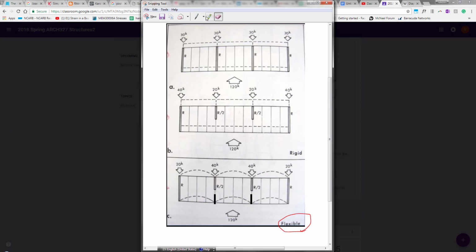So the rigid diaphragm, the way the load gets distributed among the different shear walls is purely through the linear lengths of the shear wall. We're gonna be looking mostly at flexible diaphragm, which basically, so the diaphragm is again this horizontal slab element, right? So we're gonna assume that it's gonna bend almost like a beam, like that. So because we're assuming they're flexible, so it can take deflections, and that's partially how it transmits the load to the shear wall.